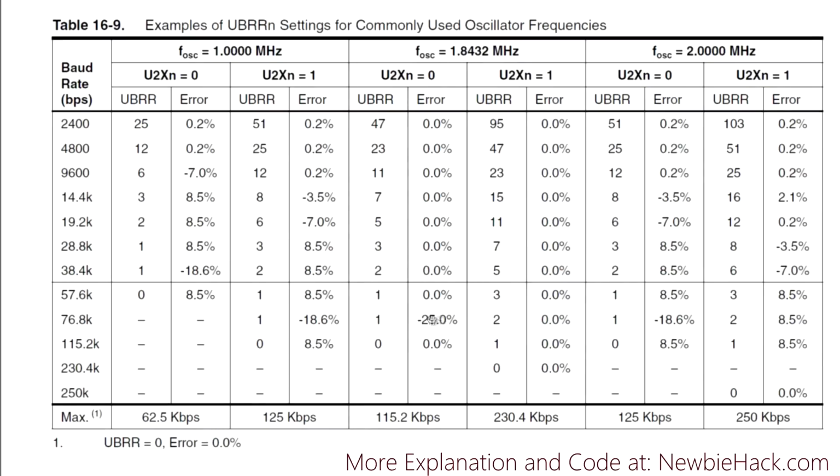And you'll notice that with the exception of this single percentage using the single speed asynchronous communication, it has a negative 25%. So we'll not even look at that. We're not even going to be interested in that one. You'll also notice that these frequencies look really strange. I mean, they're not a rounded number like the 2 MHz or 1 MHz. They have a specific number, and these are very popular clock sources because they're made for this type of communication.